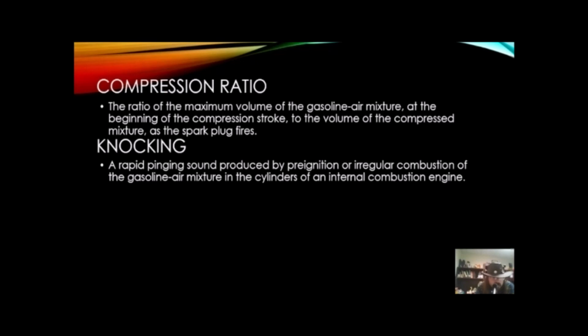This allows you to get higher amounts of power for the same amount of gasoline. You burn this, you get more power applied to the motor. You want to accelerate more quickly, you want a higher compression ratio. Essentially, when this is compressed, the further this piston can expand, the more energy you can get. Now, in 1925, the air was compressed to about a fourth or a fifth of its original volume. Now we've managed to compress the air down to a tenth of its original volume, and so we can get far more energy out. But this leads to the main problem that we deal with in gasoline.